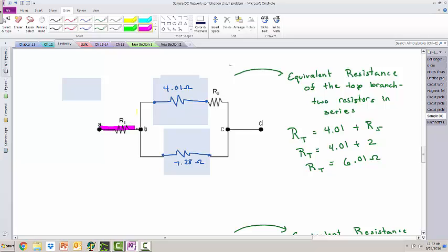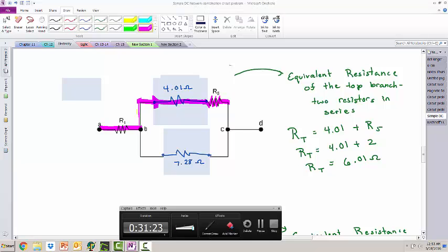So coming out of the battery, we have 4.31 amps marching through resistor 1. Of those 4.31 amps, 2.36 take the top branch and march on. Now, we don't really want to work with this equivalent resistance yet, so we're just going to let them march through that equivalent resistance. It's in series, and those 2.36 amps march on in series, so all of them go through R5. So now we know what the current through R5 is. If we know what the current is and the resistance, we can find the voltage drop and the power. So let's do it.